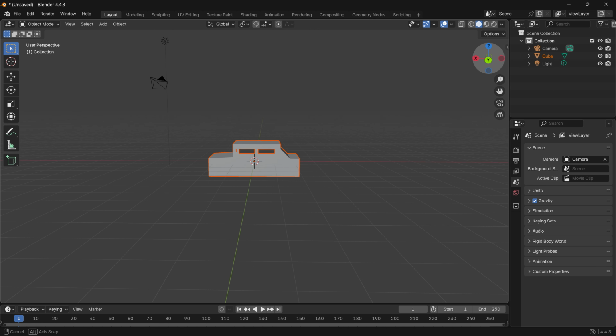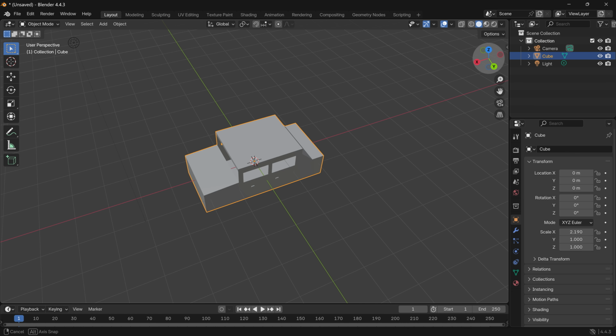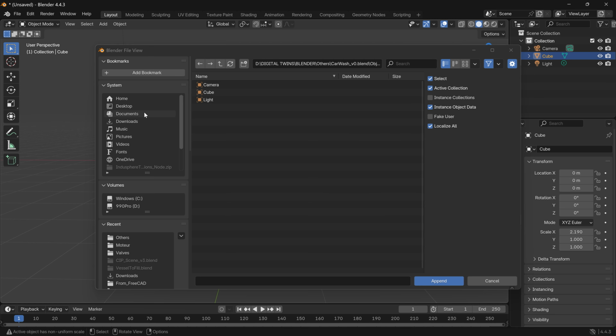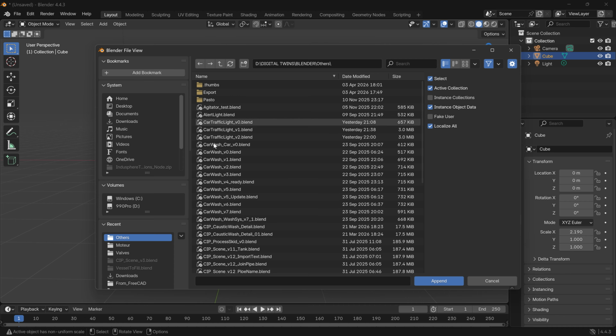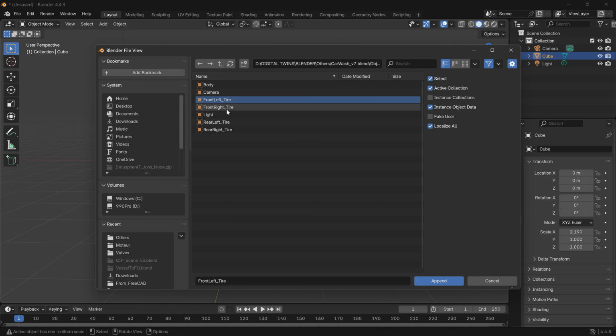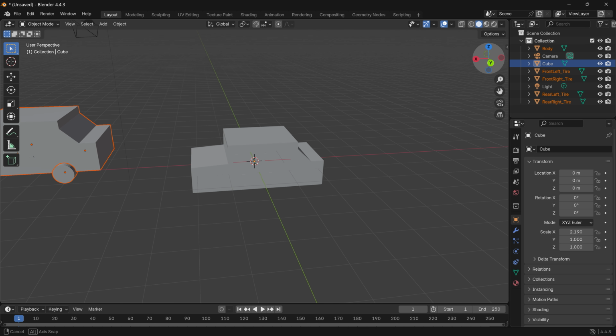Before exporting your scene, make sure your camera provides a good overall view. Having the correct orientation in Blender will make positioning much easier once the scene is imported into Isaac Sim. Also, verify object names and organize the scenes properly. It becomes much easier later when referencing objects inside OmniGraph.